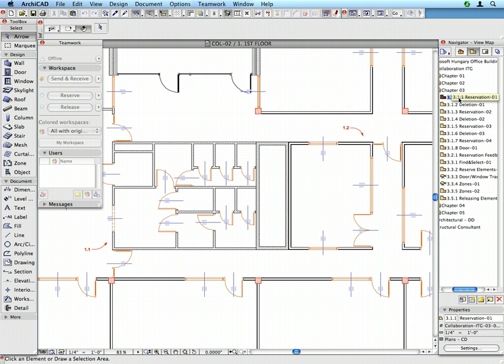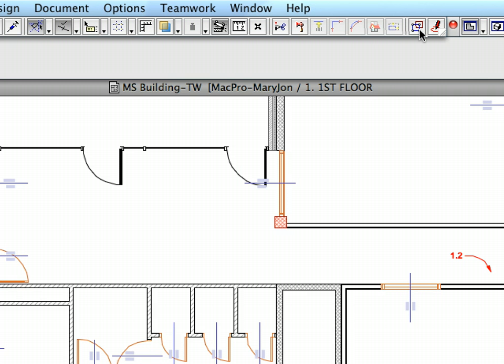This will activate a preset view which restores the floor plan at the stored zoom factor, scale, layer combination, and so on, stored in this view. You can see a red label arrow with the number 1.1 in the left portion of the screen pointing to a wall. Make sure the Suspend Groups toggle as well as the Tracker toggle is activated in the standard toolbar.